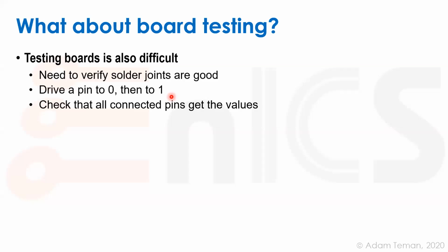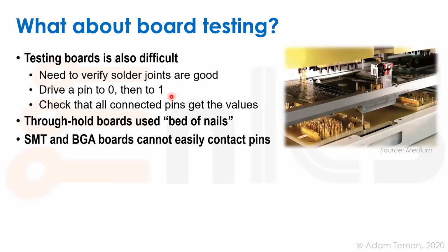We need to drive the pin to 0, to a 1. We need to check that all the connections were made. We might have many chips on a board. How are we going to do this? So actually the standard way is called using a bed of nails. You can see that this tester has all these nails, and they connect to the pins on the board, and they can check that the pins worked, but it can get very complex. And once you have all kinds of BGA boards and stuff, it's basically infeasible.